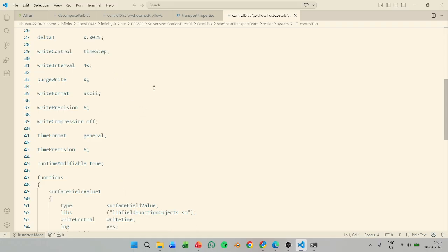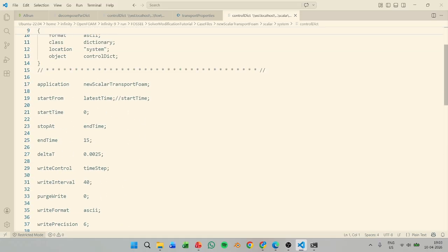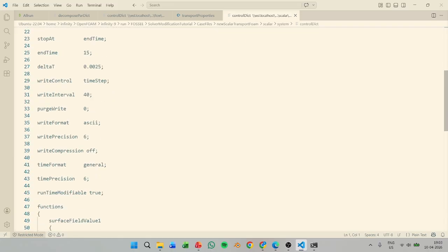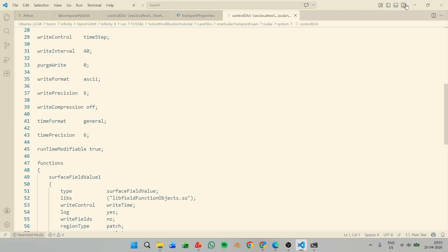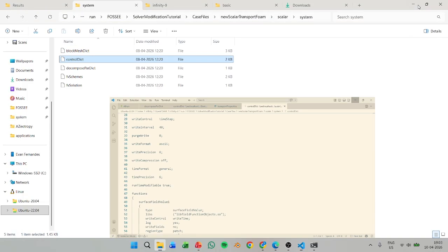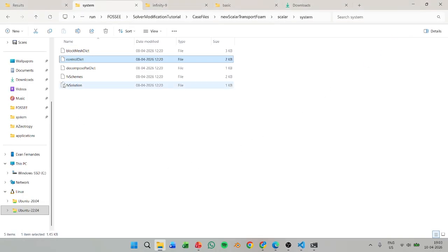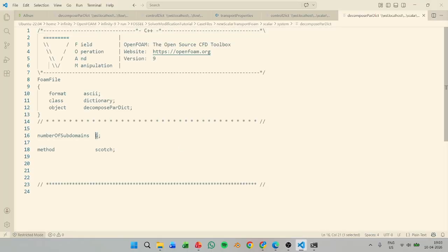Okay, so on my system, when you're running it on 6 cores, it takes around 10 to 15 minutes, not more than that. But again, if you lower the number of cores you're using, it will obviously take some more time. Okay, so keep in mind that this particular simulation will take some time, but not too much time. Okay, so again, over here we'll change this in advance. So decompose, instead of 6, we'll change this to 4.